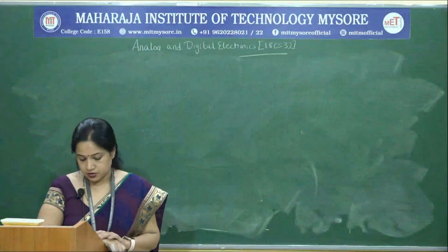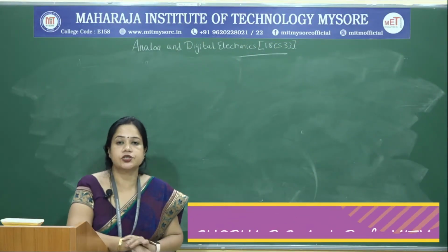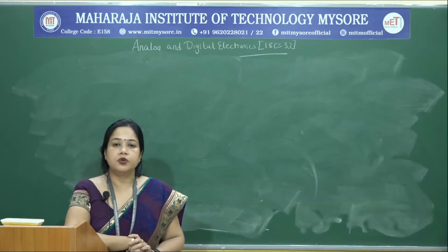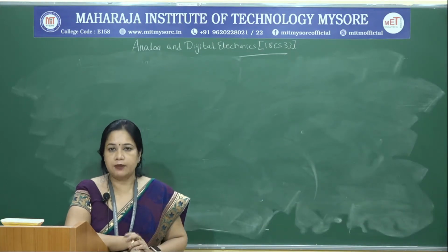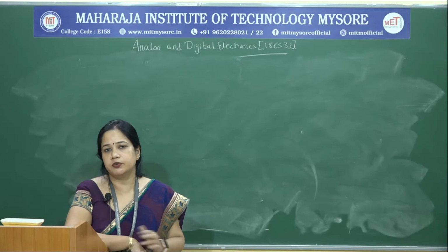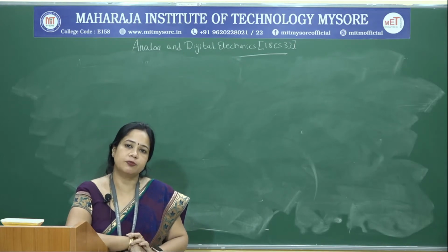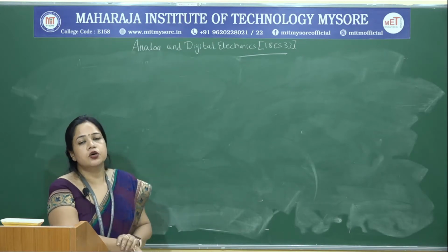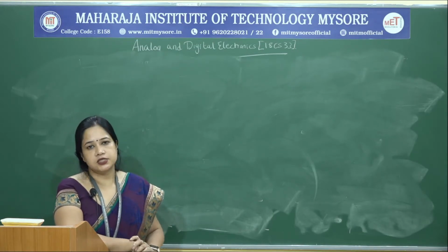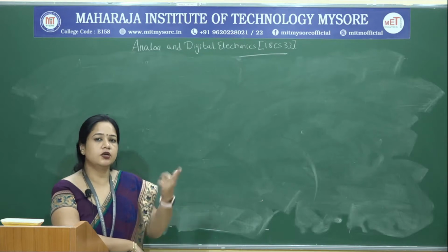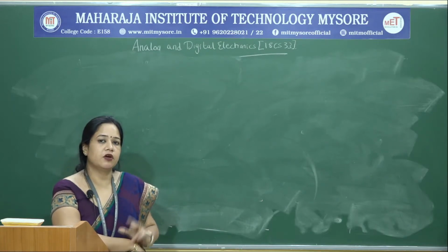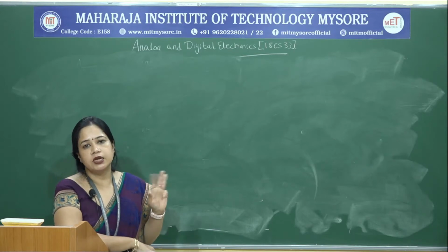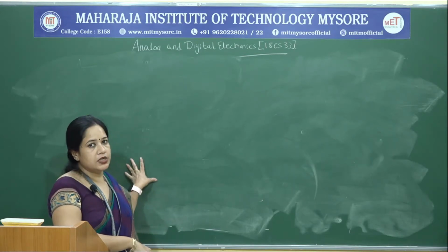So, welcome back. We will continue our discussion on astable multivibrators, and in the previous session we looked into the applications of monostable multivibrator. We had worked a few problems on monostable multivibrator, and we also looked into the use of 555 timer as an astable multivibrator. Just to recall, your 555 timer as an astable multivibrator requires 3 external components, 2 resistances RA, RB and C. We looked into the circuit diagram.